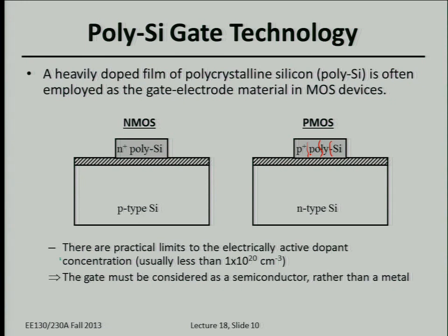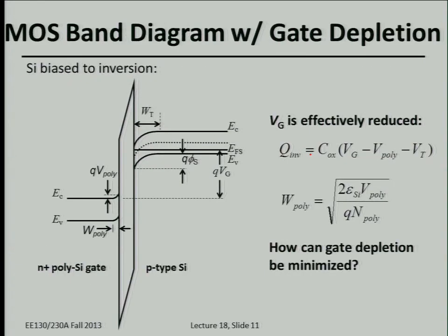Ideally, they're very heavily doped to be metallic, but in reality, as was already asked last week, they're not super heavily doped, so you actually could get depletion of the gate material if you apply a significant gate bias. That's illustrated here. Assuming that the silicon is not perfect like a metal, some depletion can occur, resulting in some band bending.